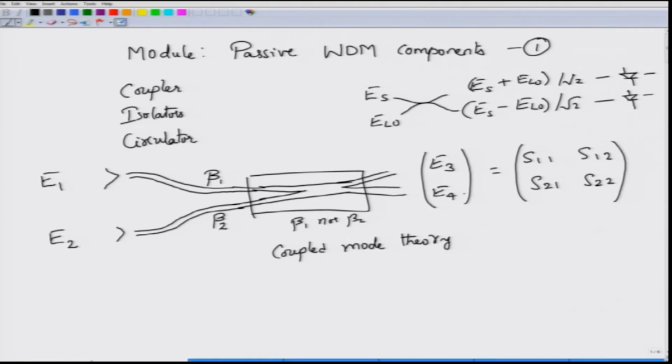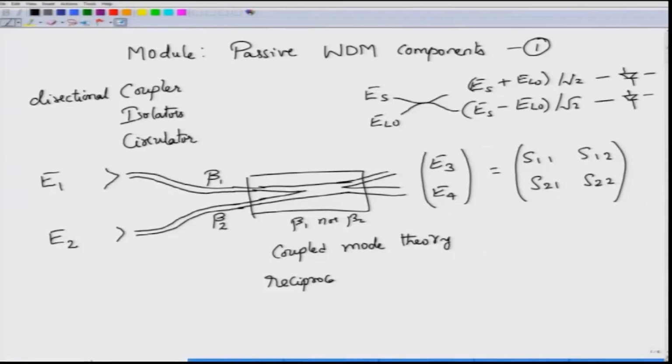For that reason this is sometimes called a directional coupler. It is called a directional coupler because there is a certain direction from its input to output. Of course, the coupler is also reciprocal. It is reciprocal because you can turn around the input and output. You can make this coupler work in both ways. So, it is like a passive resistor. A resistor is essentially a bilateral or reciprocal device. There are no fixed terminals for the resistor to be put inside a circuit.